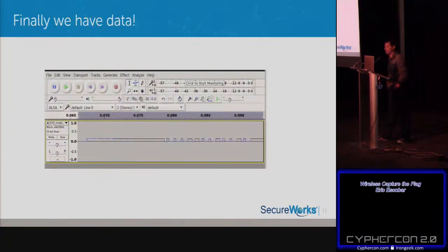What's really awesome about this is that you can tune your software-defined radio and export the signal to a WAV file. This WAV file can be opened up, and I like to use Audacity. If you tune it right, you can see the blips and bloops as they come across the screen, which is really cool. The old school way of doing this was to print it out with the time, get some graph paper, and mark out where the ones are and where the zeros are, and then you could generate that signal. If you knew the timing of it, you could replay it back.